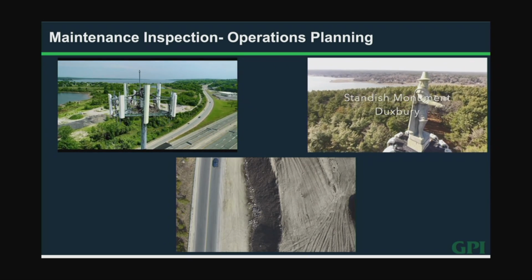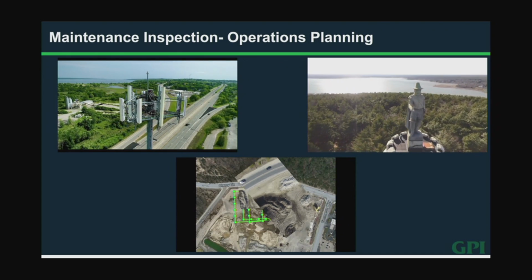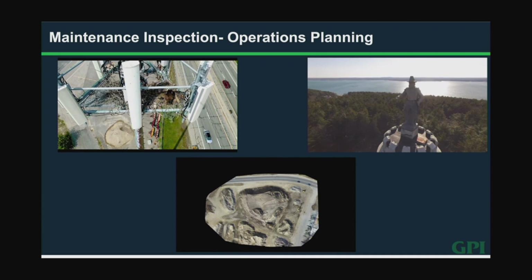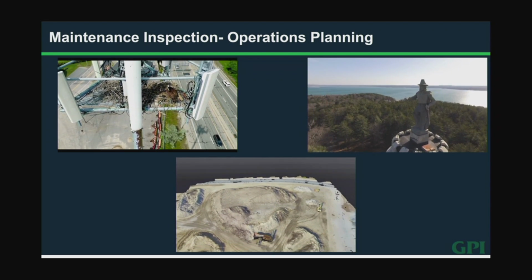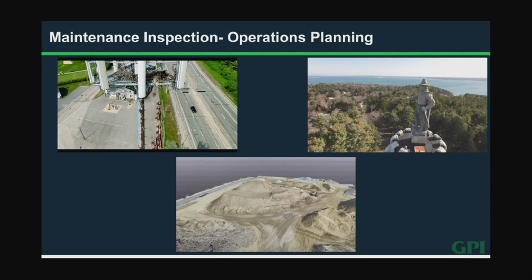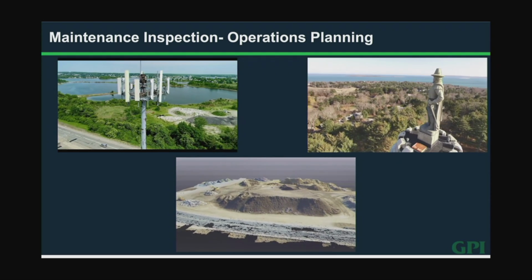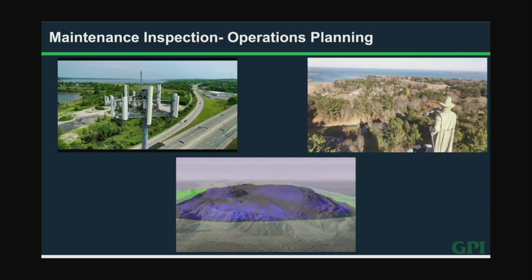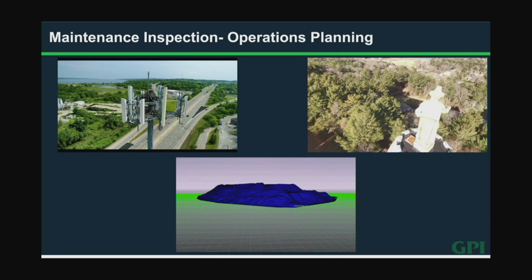And so then we brought it back to the office. We processed all the ortho images and brought them into CAD, and realized you can very easily do a volumetrics. So we gave them that, and they were fascinated by it. They're like, "Geez, we usually send guys out there literally with GPS units on top of the piles, and that's how we do our quantities." So that led to doing a salt deposit for Mass DOT, where they store their winter salt, so they could get volumetrics of the salt use. And you can imagine, just again, the other uses for these things.